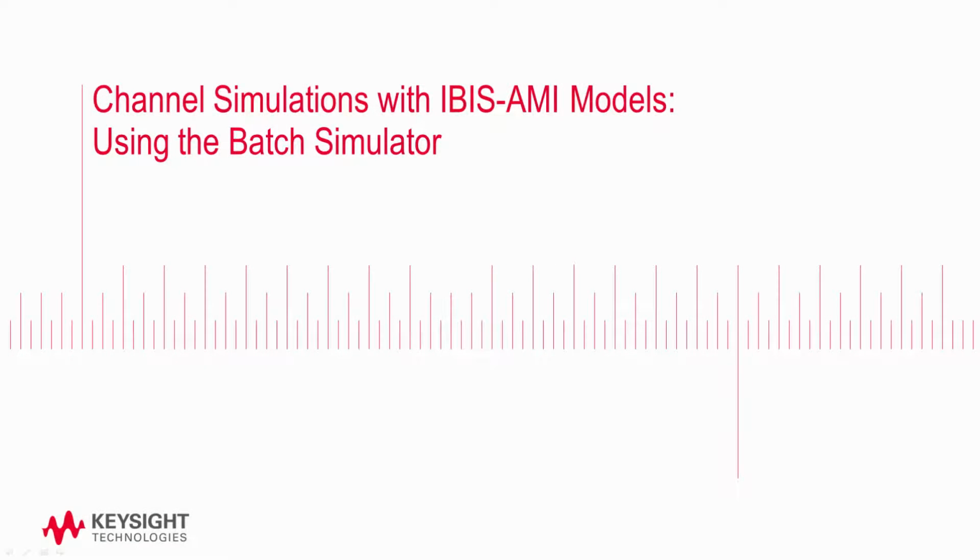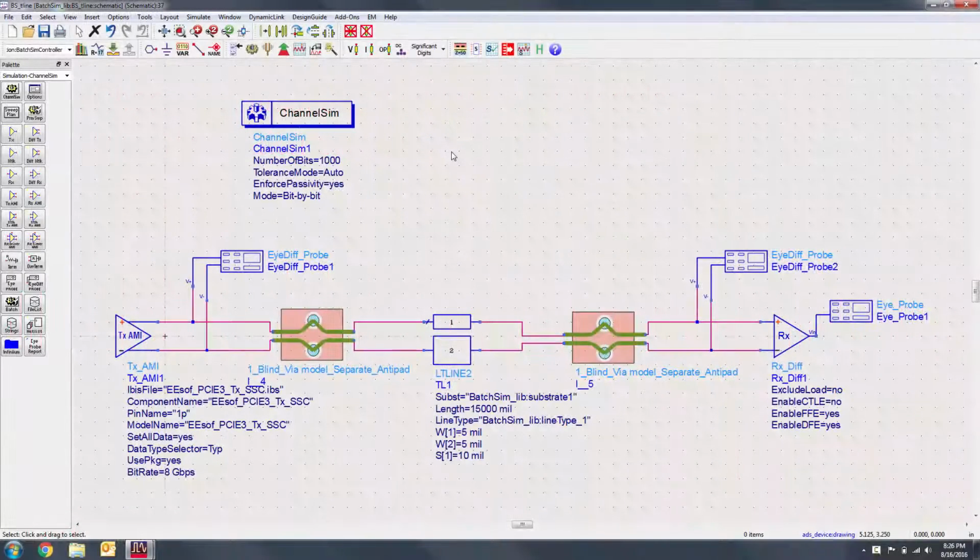Running batch simulations can greatly speed up the process of running tests on your channel simulations. This video will show you several ways to run batch simulations on your parameters for both ADS modeled and IBIS-AMI modeled components. We'll then also look at how to set up your data display to easily look through different batches simulated. Here's the channel we'll be using for all of these simulations.